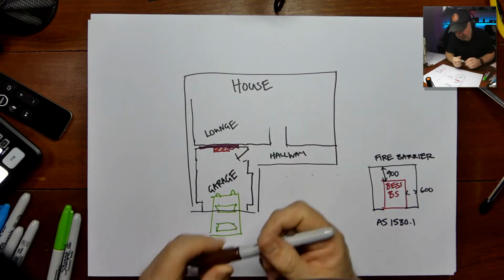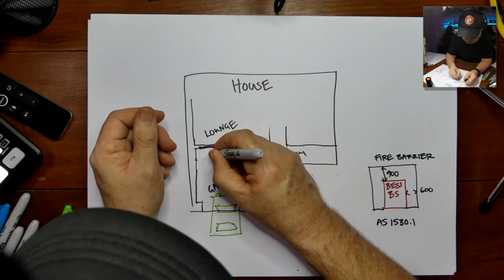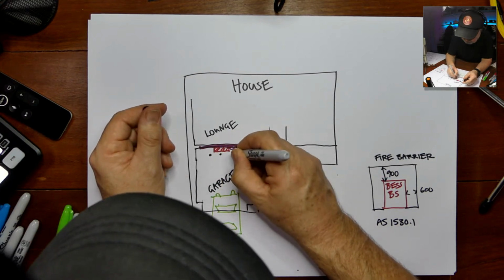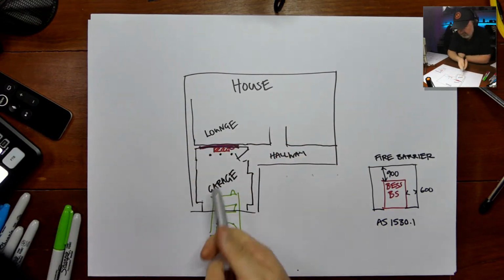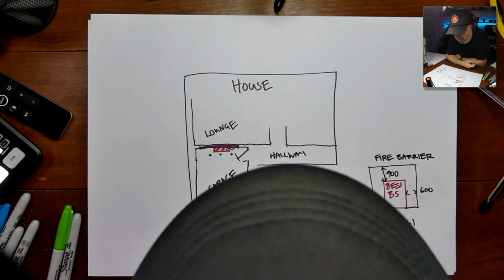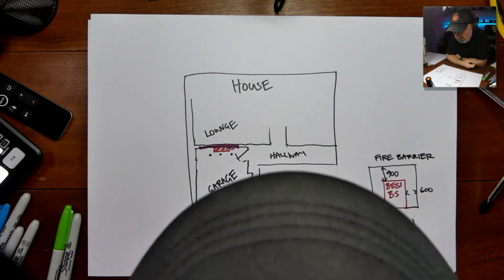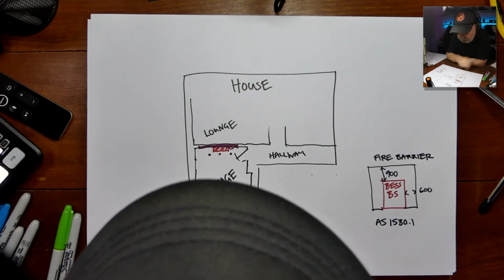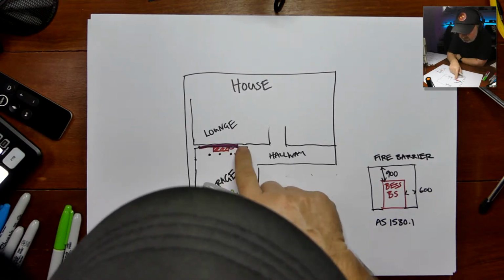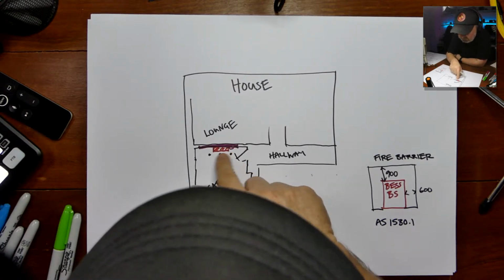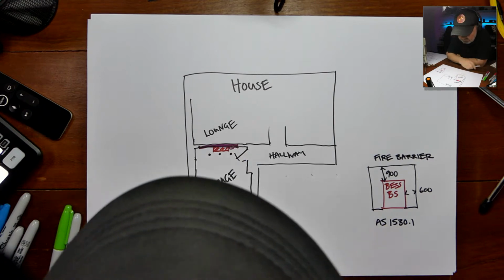So you'd have something like bollards. So you might have some bollards in front of that system. And if that has doors on it, you're going to have bollards that you can remove for maintenance purposes, or some are hinged to get access to that. So this is probably not the best location because of the extra cost to the fire barrier and the bollards.